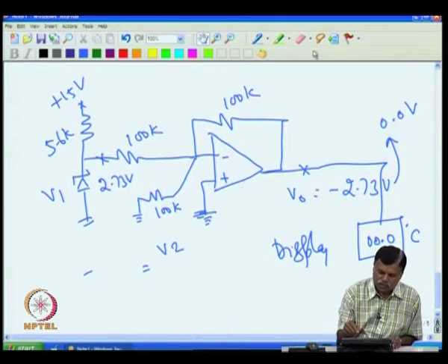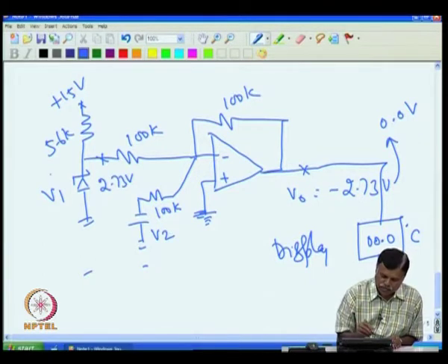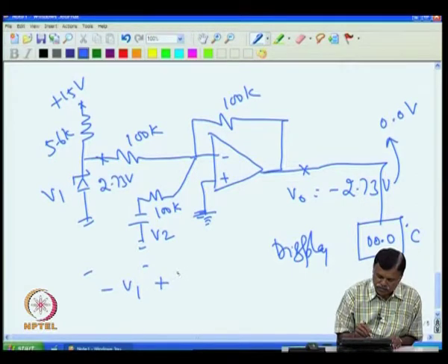So, already those are familiar. Maybe you need not struggle so much. You can say that the two voltages here, this is V2 and the other one is V1. The net output is V1 and the gain is 1. So, V1 is anyway inverted, so output will be minus V1, and for V2 again the gain is 1 and that is again inverted, so I will have plus V2. So, if V1 and V2 are equal, then output will tend to 0.